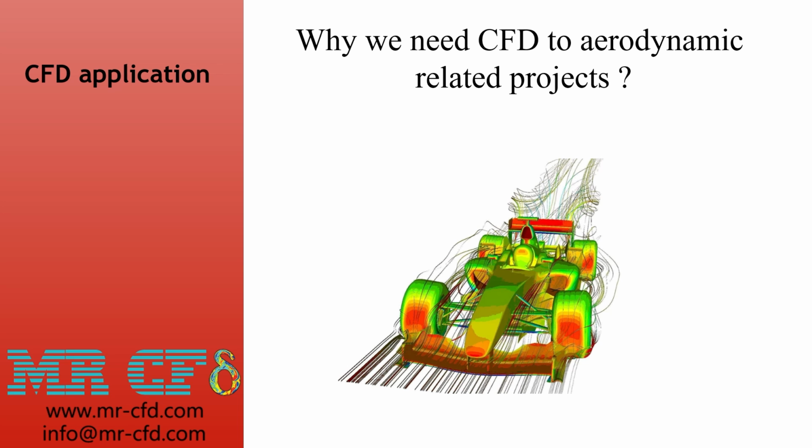And as you probably know, the vortex is one of the key elements that we investigate in designing the wing of an aircraft. We need to see where the separation occurs, and we use tools such as vortex generators to create a vortex to avoid that separation.